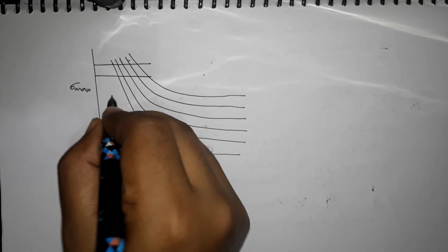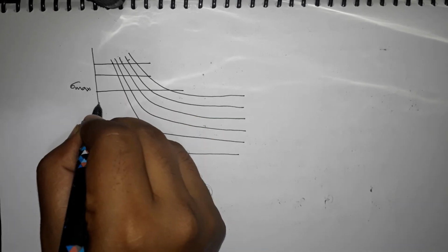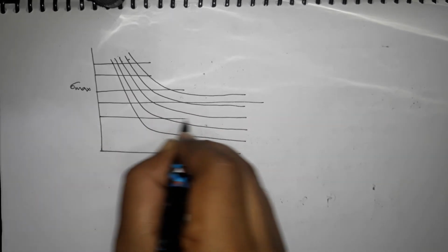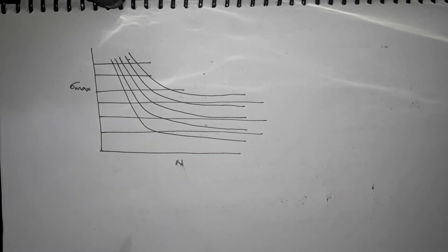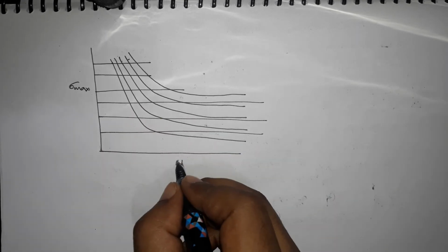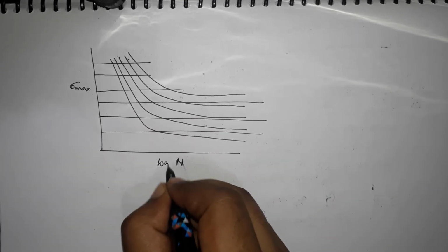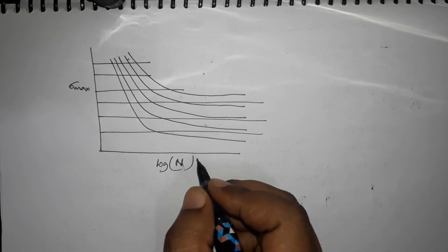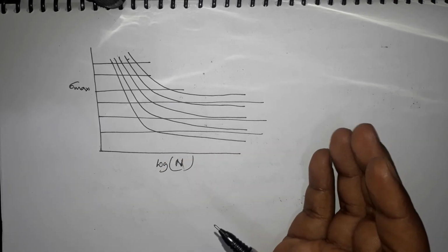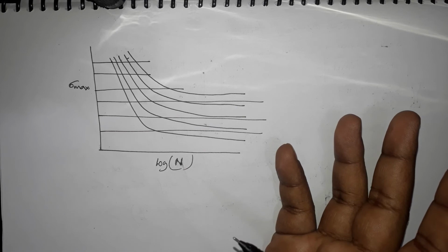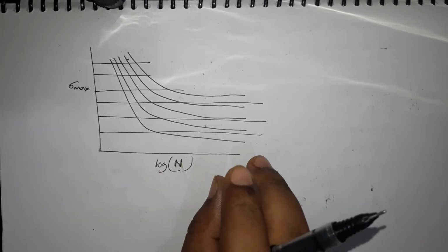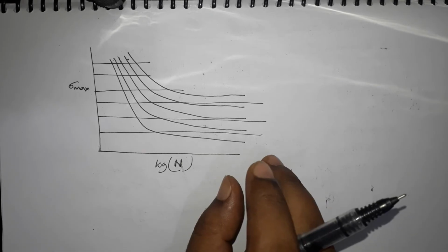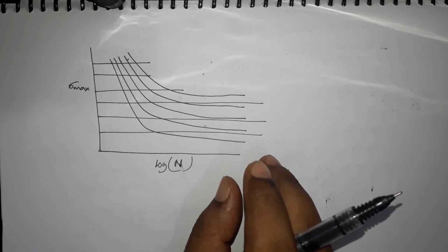Okay, so we have different stress levels and we are performing many tests. Okay, and we are getting obviously different values for the number of cycles for which the materials or the specimens are breaking, because each specimen will have its own fatigue property. Okay, because it will have a unique number of defects in it and a unique number of surface defects on it.